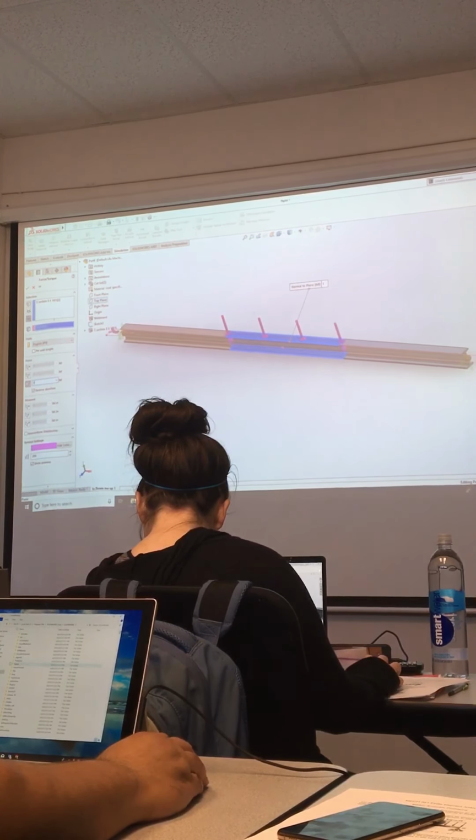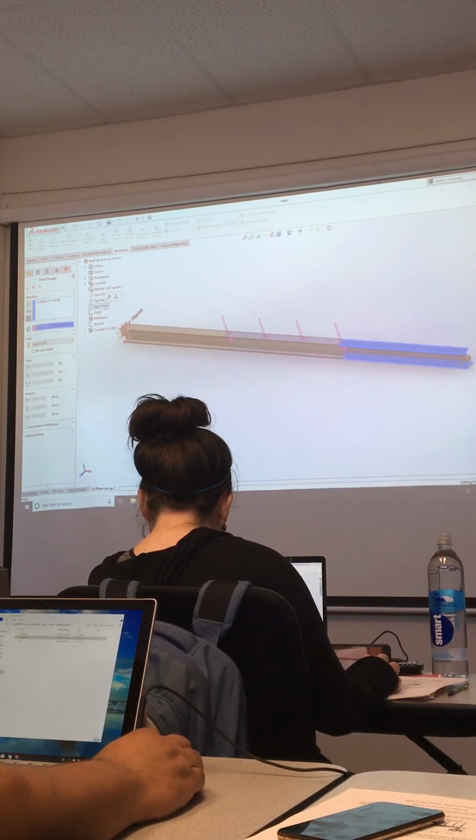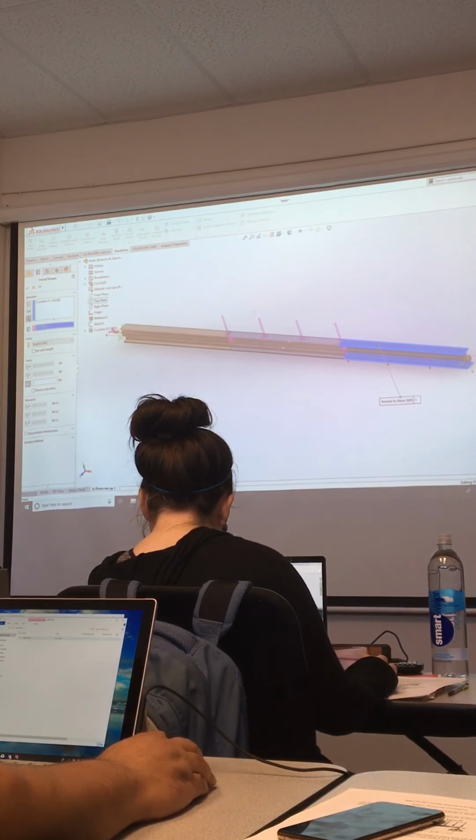Okay, and I've got that force on there, and of course, if I can do it once, I can do it twice. And we're gonna go pick, again, we have to select on the beam option, pick the beam, need a reference geometry, and I typically pick one that gives me an easy way to pick my orientation.